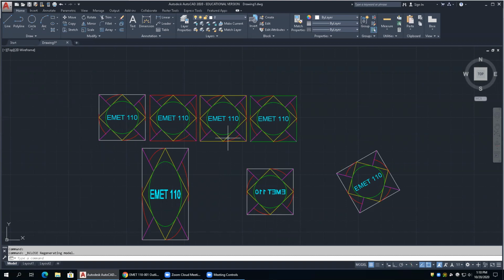So the way to export anything out of this drawing, that allows you then to bring it into another drawing, is to use a command called WBlock, which stands for write block. And interestingly, I don't know why AutoCAD doesn't use this tool much. They don't have that up there in the block section. So in the block panel here, you won't find it. This is kind of a hard one to know unless you just know it. I know it because I teach it, and I've been using it for a long time.